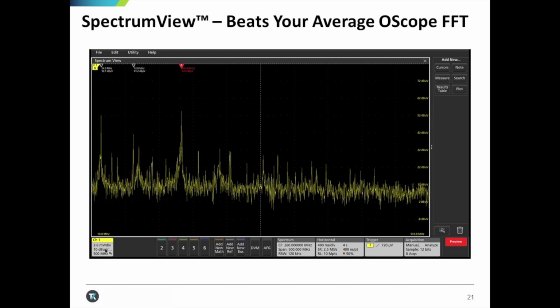In addition, the IQ data can be exported from the scope and reanalyzed in SignalVu-PC offline for more in-depth vector signal analysis. In all, and I'll talk more about this later when we get into discussing periodicity and coincidence of signals, the MSO series of oscilloscopes and their Spectrum View functionality allows for time domain and frequency domain correlation with other signals. This ability to simultaneously display time and frequency domain views of the same signal with independent acquisition settings in each domain is an easier, more repeatable means to EMI debug and moves towards more efficient system analysis.